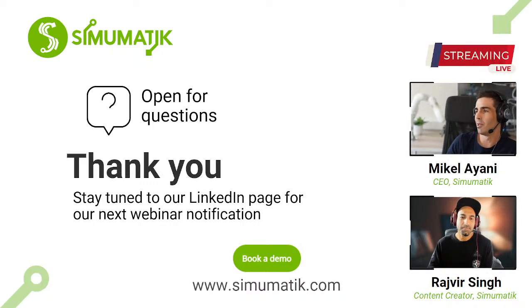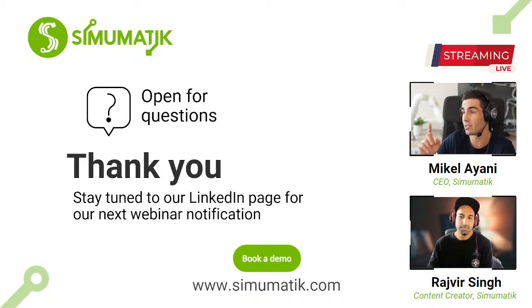Yeah, the PLC usually is what is called the slave. We tried a little bit, but it was a bit difficult. So we were thinking, let's wait until someone documents how to do the setup, and once that works, it should be as easy as what you show. I mean, you have done integrations with Delta PLCs. I've done integration with Codesys. It's pretty seamless. You just have to map the addresses and follow the manufacturer's guidance on how to set up the Modbus. And Simumatik doesn't really care which PLC it is as long as it's compatible with Modbus TCP.